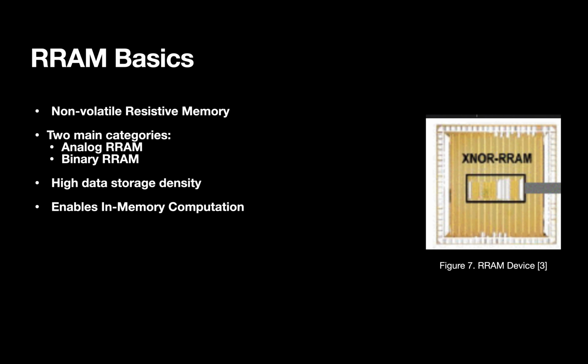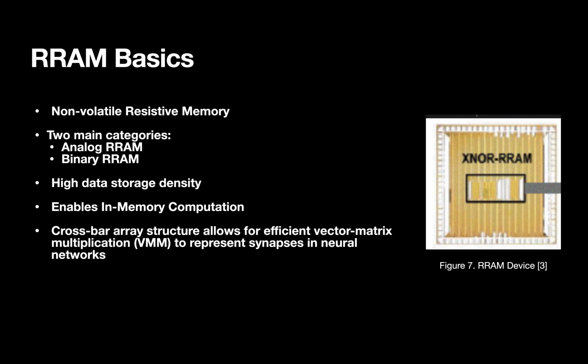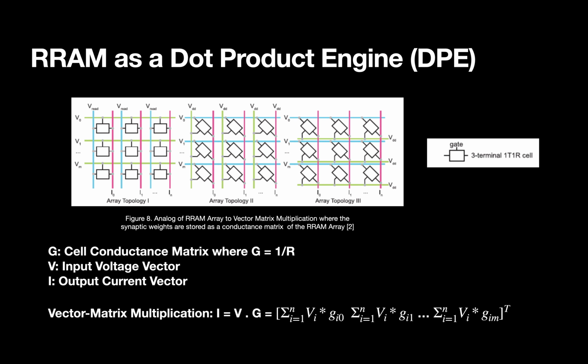By combining complex logics such as vector matrix multiplication, which is used to represent synapses in neural networks, with RRAM, a fast, energy-efficient computer is created which can execute heavy logical workloads. The RRAM stores binary inputs as resistances or conductances before performing computation. And to allow in-memory computation, voltage is applied to these resistances. The output current represents the logic operation result.